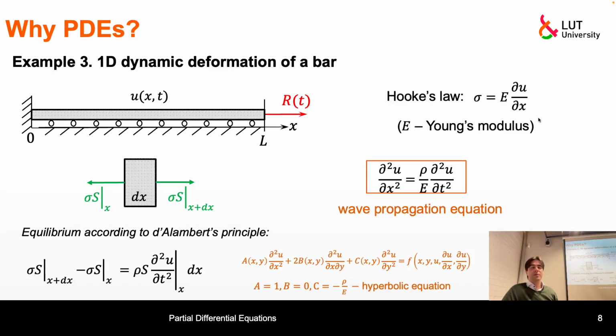It has to do with assumptions in linear elasticity, because it might be a little bit more complicated. Stresses might depend on the full strain tensor, like if you use a Green-Lagrange strain tensor, for instance, or there are some other measures used. There are quadratic terms. So strains, something that produces stresses, may depend not only on this derivative, but also on second-order terms of those derivatives. You mean even for this 1D problem, there could have been some higher-order derivatives involved?